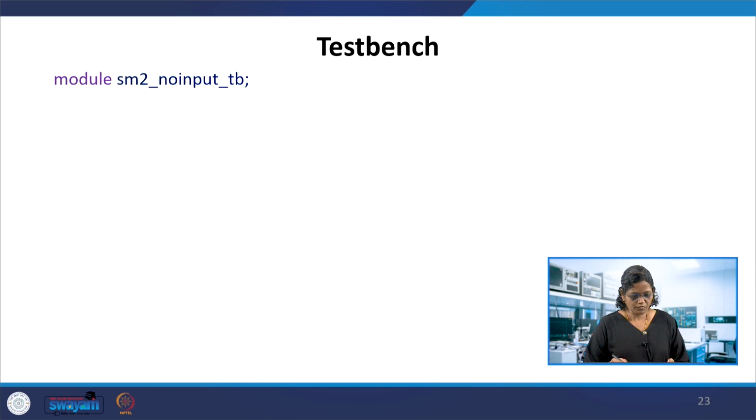So this can be very well used as a counter design. If you decide on a counter example, suppose it is a 3-bit counter counting from 0 0 0 to 1 1 1, just define these states as A B C D E F G H, and then move over the clock edge.